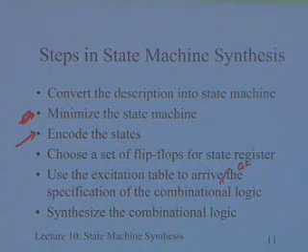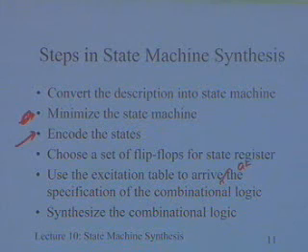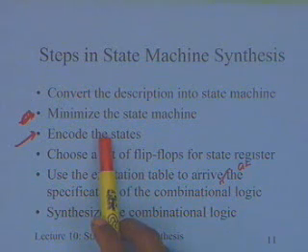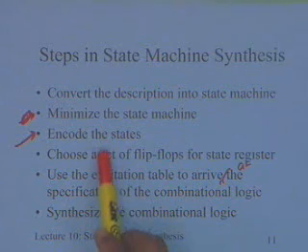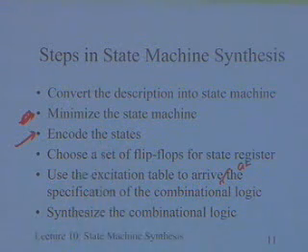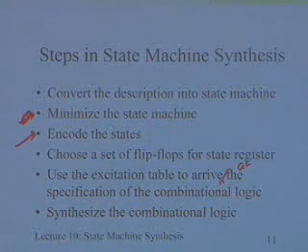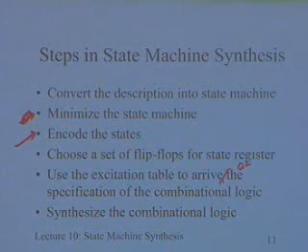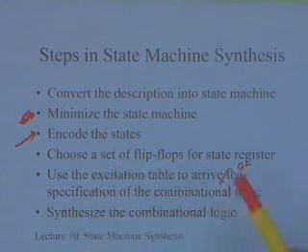Similarly with the flip-flops, as I said, typically you use D flip-flops, but if there are a lot of transitions which are counter-type transitions, transitions which mainly require toggling, so that most of your bits do not change, but if at all they change, they just toggle, it is like a counter type of situation, then you try to use T flip-flops. Otherwise, by and large one uses D flip-flops.